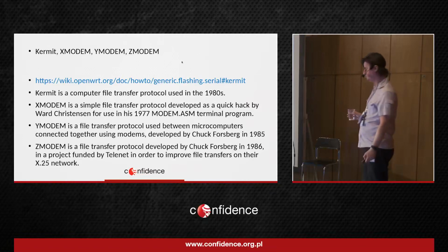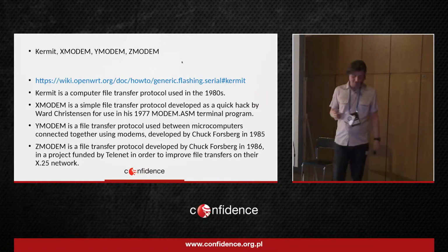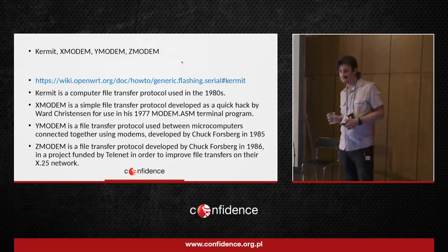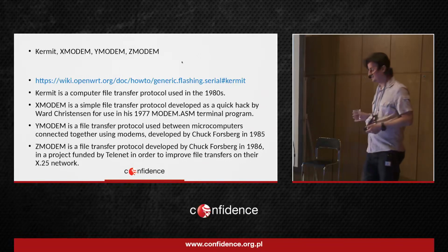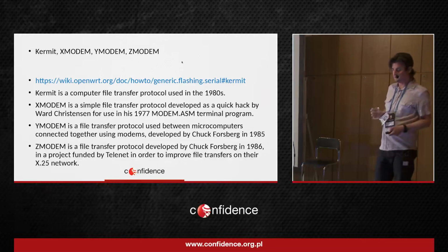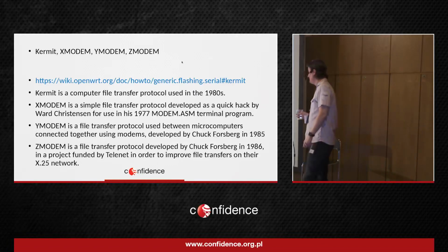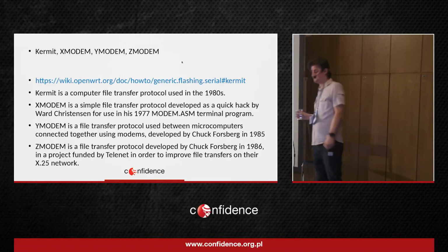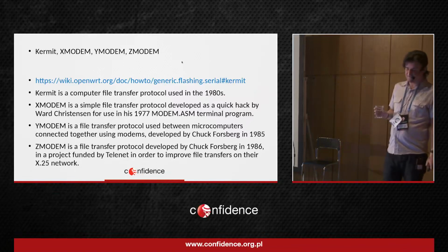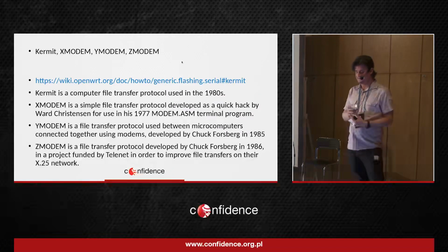Okay, so what can we use to transfer the firmware image to the device? How can we run the kernel? Because from U-boot, we often will not have access to the Wi-Fi controller. Often the device doesn't have Ethernet ports. So the only method that we have is using a very ancient file transfer protocol. This was popular in the 80s, probably, for transmitting files between modems.